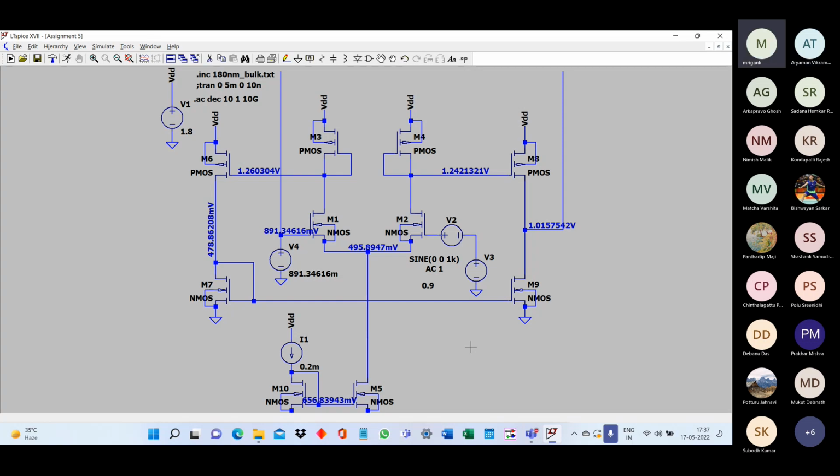So now you see that overall we have increased the channel length for the output stage, and M6 and M7 have also been sized up in the same manner. From the DC condition point of view, if you remember, the bias current in M5 was double that of the bias current provided in the output stages.